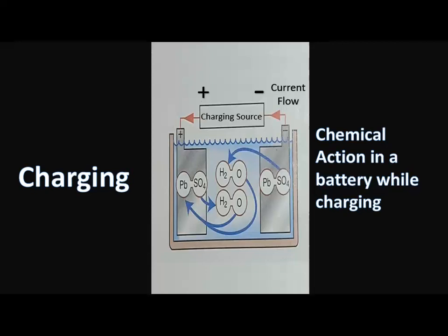Low maintenance batteries are designed to minimize heat and water loss. The filler caps may be removed to add water to the cells. In many batteries, the electrolyte should be at a split ring around the indicator below the filler cap in each cell. The water level must be above the battery plates. The average interval for adding water to a battery is approximately 15,000 miles. If the battery requires frequent addition of water, the charging system voltage may be too high.